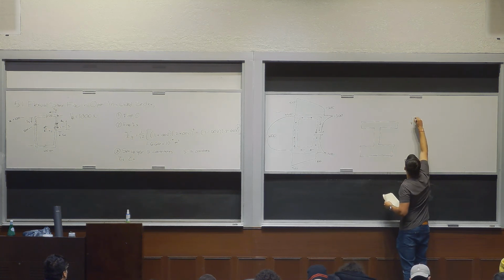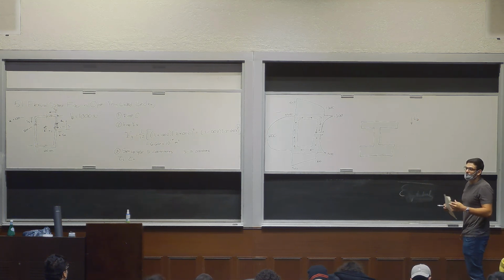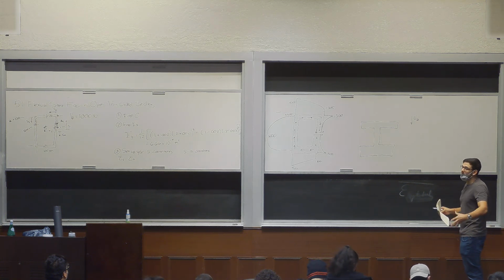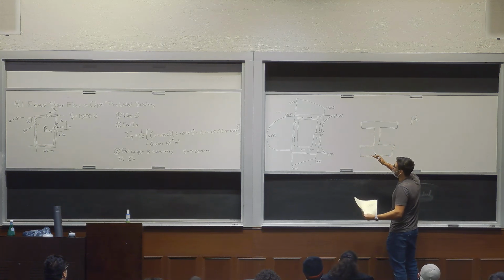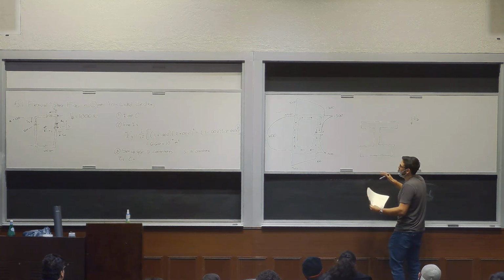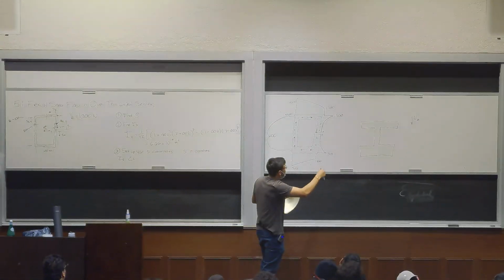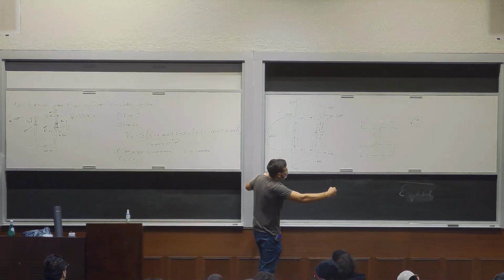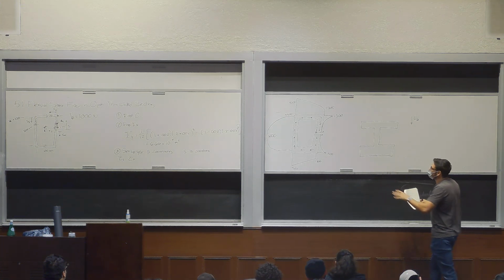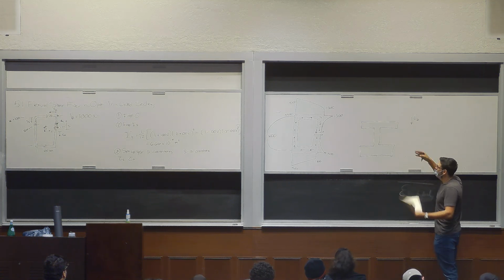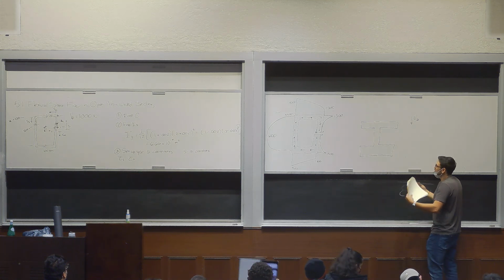Okay, we have VZ. Another thing to clear up right now. So far, we haven't talked about the location at which VZ is being applied. That matters because if VZ is acting here or here or here, it's going to produce different results as far as torsion goes. It's not going to produce different results as far as this distribution goes, but you can imagine if this VZ is applied at a very far location, it's going to also twist the cross section. We'll talk about that in a little bit. So far in these problems, all you're being told is that there is a VZ, not where it's acting. Eventually we'll have to find where it's acting or where it should act so that it doesn't produce torsion.